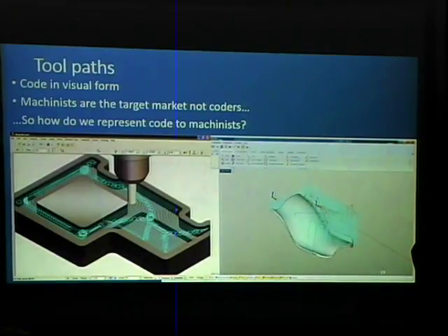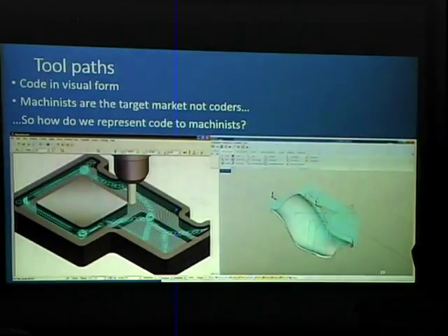They also allow us to make more complex parts. That injection mold you saw is not realistically something you're going to be able to machine by hand. It's very, very complicated. You're going to rough it out by hand, and then you're going to come in and probably manually finish it with a grinder till you get close to the right shape. With the CNC machine, it doesn't care about the geometry we give it. It will break it down into numbers, into locations, and it can then implement that into something that is not something I could machine by hand or anybody could machine by hand. All right?